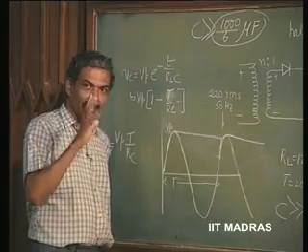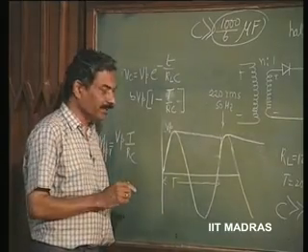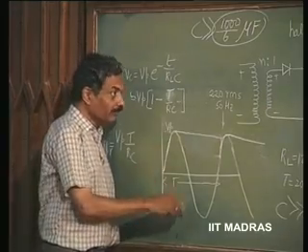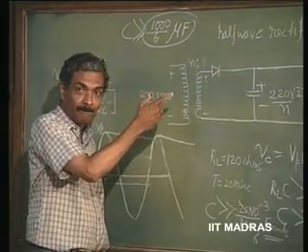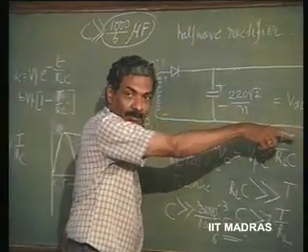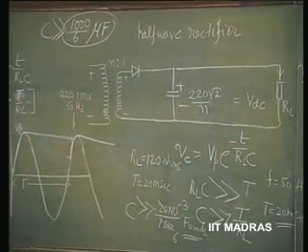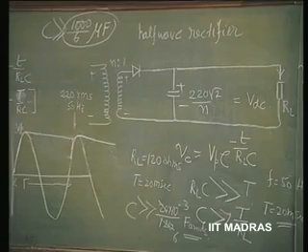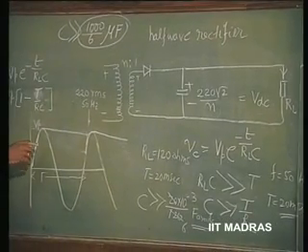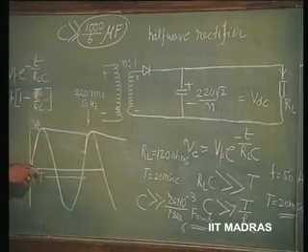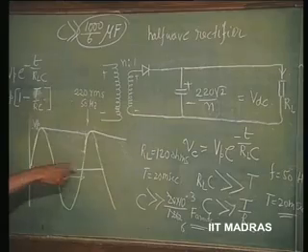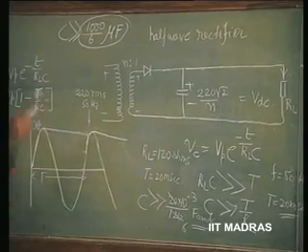We would like to make a pakka DC supply voltage for our application. So we have made use of the peak detector and put a load across it and seen how the peak detector changes its behavior. That is a better way of designing a DC supply than trying to understand it in terms of half wave rectifiers and then putting a capacitor.